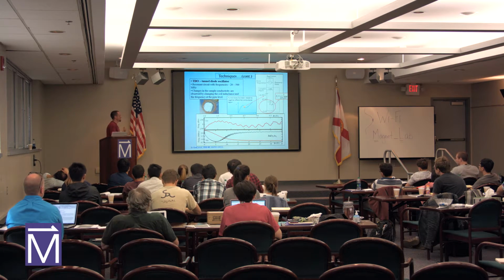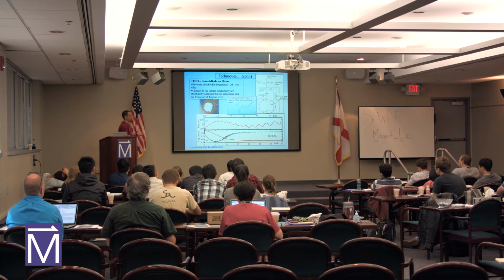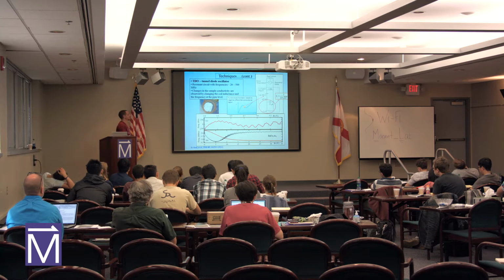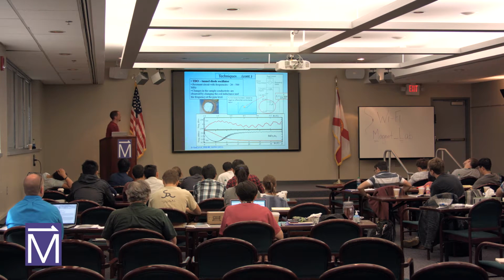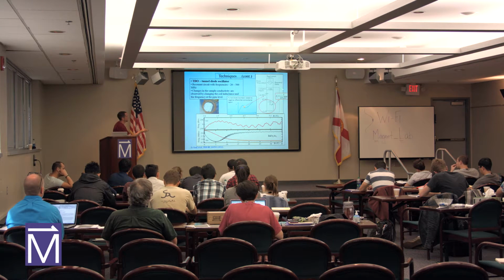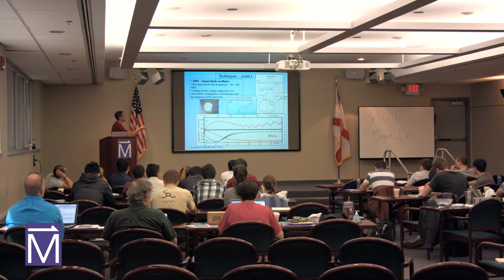Okay, say you have difficulty putting contacts on your samples, or it's impossible in some cases. We also have contact-free ways of measuring quantum oscillations. In this case, we use a TDO circuit, TDO being tunnel diode oscillator. This is a photo of the end-on view of a coil of wire with a single crystal in the middle. And this coil of wire makes an inductor that's part of this resonant circuit. This dashed box shows the part of the circuit that's down at low temperatures, including the tunnel diode shown here.